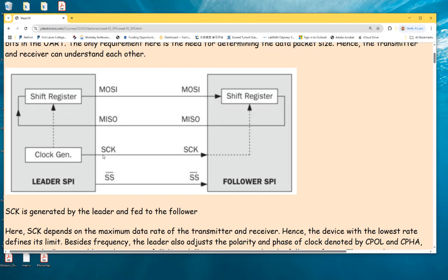There are not too many protocols we need to learn. During an interview, you tell them you have done so many projects, and they ask, if you see SCK, is that I2C or SPI? If you don't know, you won't get a job. So if you see SCK, it's going to be SPI. For the clock in I2C, it's SCL, serial clock, not SCK.